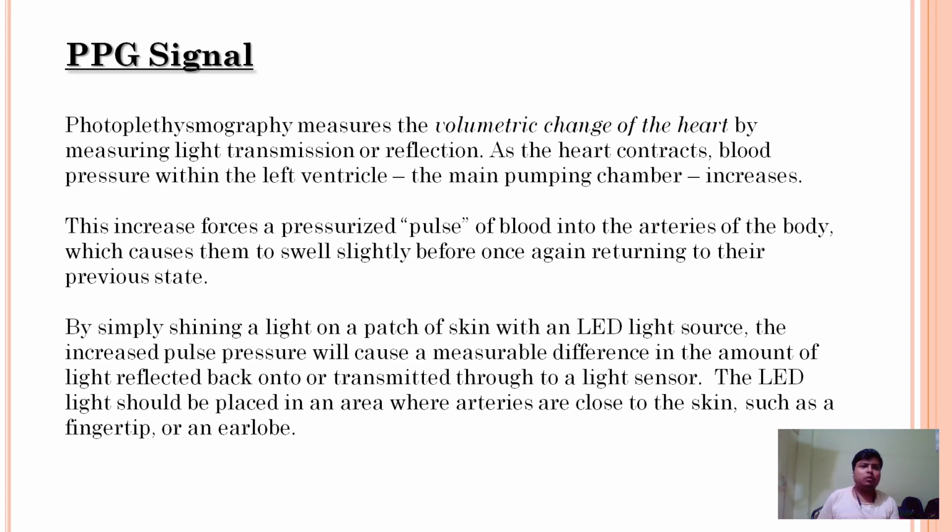So let's get to know what a PPG signal is. PPG stands for photoplethysmography signal, which measures the volumetric change of the heart by measuring the amount of light transmission or reflection. As the heart contracts, the blood pressure within the left ventricle of the heart increases. This increase forces a pressurized pulse of blood into the arteries throughout the body, which causes them to swell slightly before once again returning to their previous state for a certain amount of time.